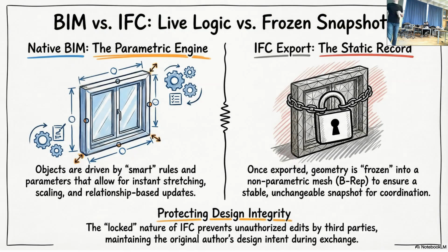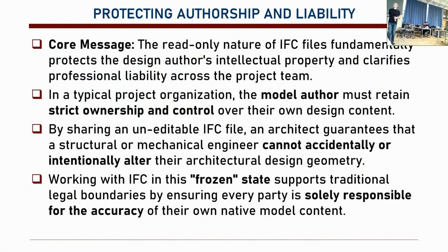It's not flexible. This is a good thing, because it prevents unauthorized edits by third parties. Okay? So the engineer cannot move your window. The engineer cannot change your wall thickness on their own will. If you give them your Revit file, they can change something and you cannot prove that they have changed it. Okay? But with IFC, they cannot. They have to rely on it. They cannot accidentally or intentionally change it. It's read-only. As a model author, you have strict ownership and control.